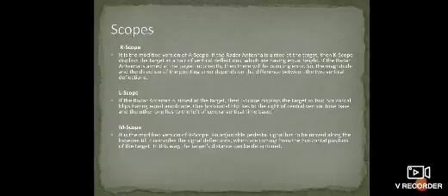It is a modified version of the A scope, and an adjustable pedestal signal has to be moved along the baseline till it coincides with the signal deflections. The M scope is very rarely used, but in this way we can find out the target distance. So when we use it, the target distance can be easily determined by the M scope.